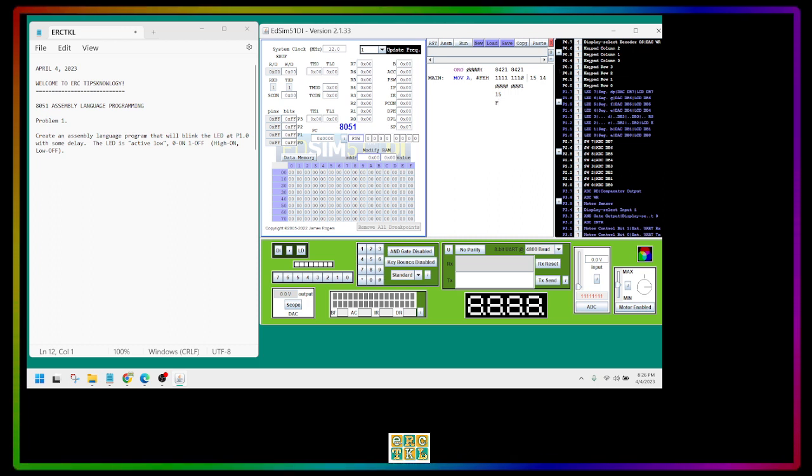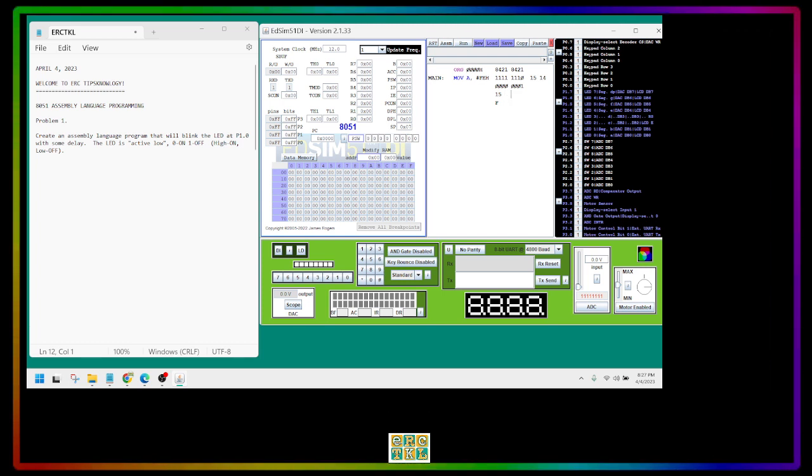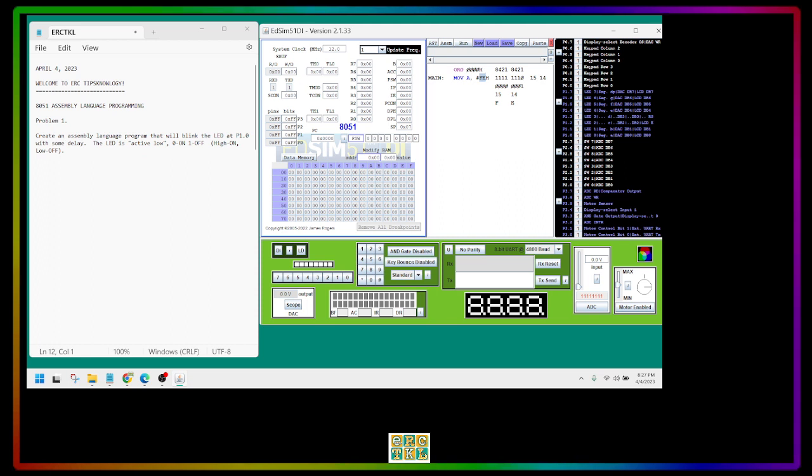Now, for the 1110, it's actually 8 plus 4 plus 2. That will be plus 1, but plus 1, we will not do plus 1 because it's 0 here. So 8 plus 4 plus 2, that will be 14. And the 14 in decimal, if you convert it to hexadecimal, will be letter E. That's why in our program, we have to write FE. This is to turn on only the first LED on the rightmost side of the 8 LEDs. That is position 0. This one. This position of the LED.